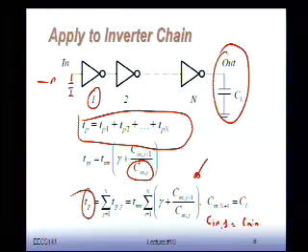Now we have an expression. Once I have an expression, I can start playing around with this. The way you do this is, if you look at it, this has a number of parameters. The parameters are basically the sizes of your n gates, which is actually n minus 1 gates, because this one is given. Its minimum is 1. So I have n minus 1 parameters that I want to optimize. If I want to minimize for those n minus 1 parameters, how would I do that?